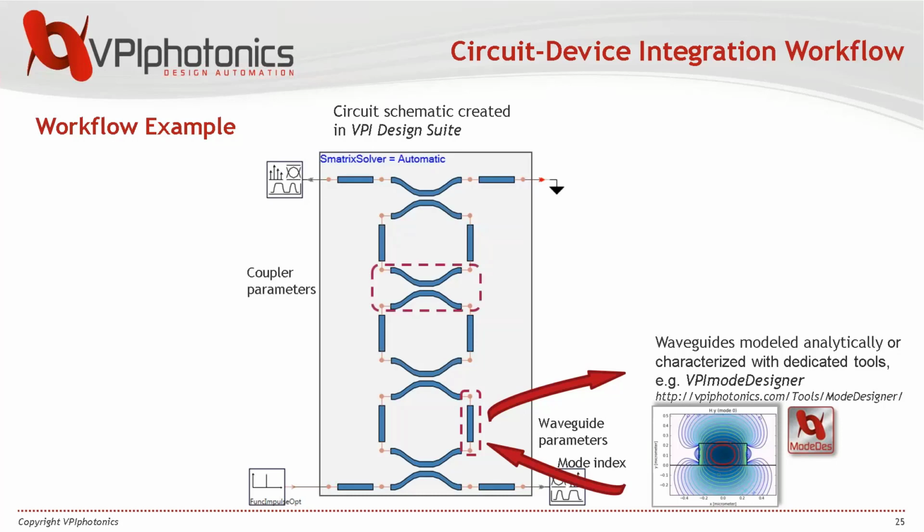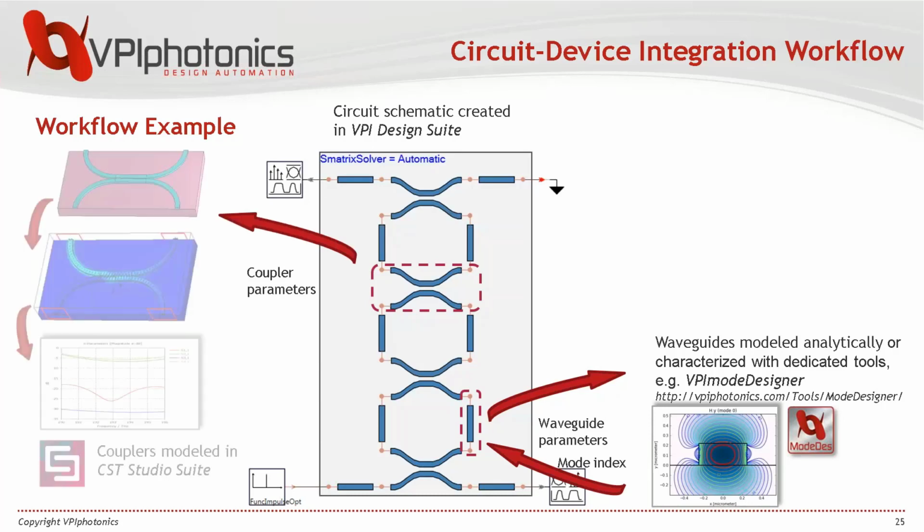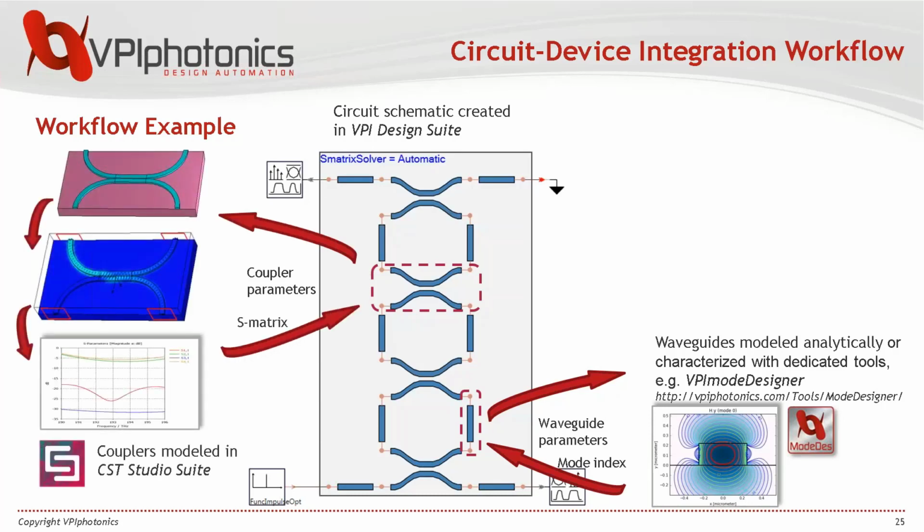But for more complicated components, such as couplers, in our case here, we need to use sophisticated device-level tools such as CST Studio Suite. And so we run simulation for preliminary created projects and extract S matrices, and have them as input for modeling couplers in the circuit simulator.